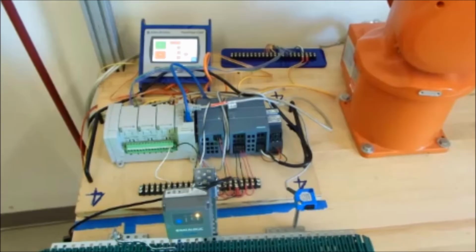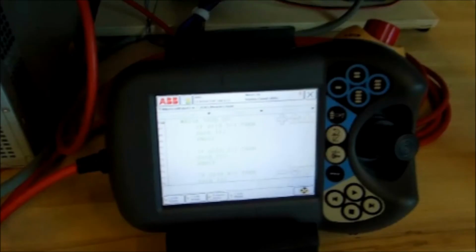Here we have the controllers, the HMI and the screen, which is currently being glared out. Here we have the PLC and the 24 volt power supply and a 5 volt converter. And on the output side we have 3 outputs, which actually go directly to the controller for the arm, which I will show you in a second. But all the other stuff is wired directly into the PLC. And here we go.